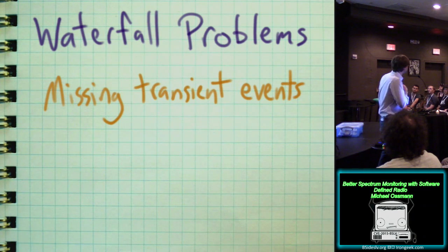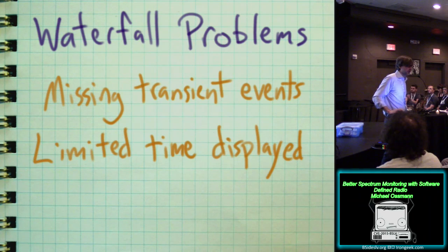And you can completely fail to observe them even if they're right in the middle of your waterfall display, because you didn't happen to get lucky enough for one of them to happen at the right time, so you get a little tiny blip in one horizontal row of your waterfall. Wow. So transient events are very difficult to observe with this type of display.